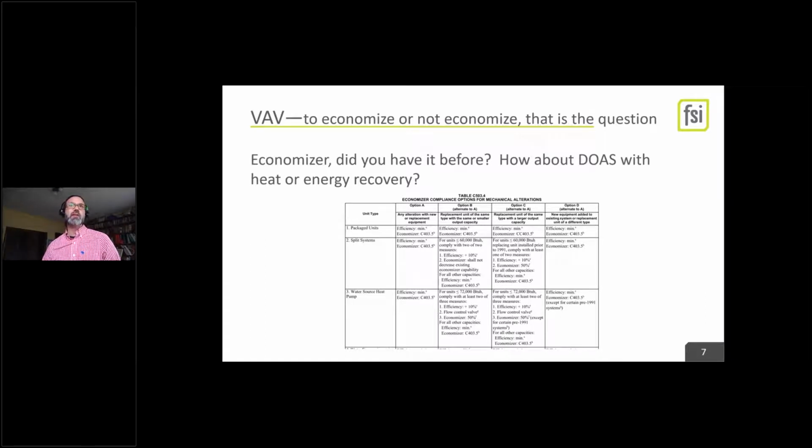If you can't get to an outside wall, it's really hard to put a larger duct to an outside wall. You don't have enough air intake room. You aren't actually on the roof level, you're in the basement. There's all sorts of reasons it could be difficult. Your option is in Chapter 5 to either increase efficiencies or have partial economizer plus some efficiency gain.